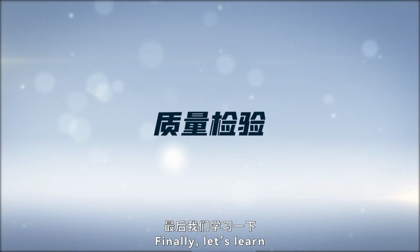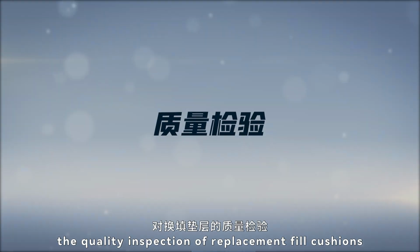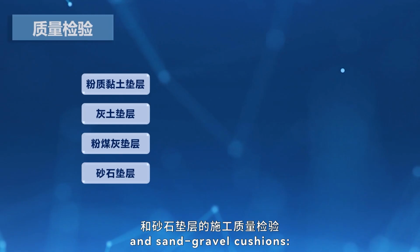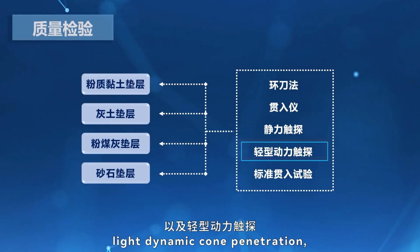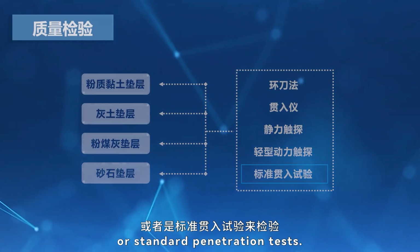Finally, let's learn the quality inspection of replacement fill cushions. For silty clay lime soil, fly ash, and sand gravel cushions, use the ring knife method, penetration meter, static cone penetration, light dynamic cone penetration, or standard penetration tests.